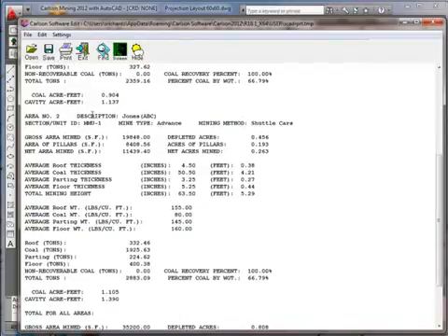One measurement in here that's very interesting is the cavity acre feet. This number represents the volume of the void that's been excavated. So if it were ever filled with water and you had to pump it out, that is the volume of water that would come out of that area for that property owner.